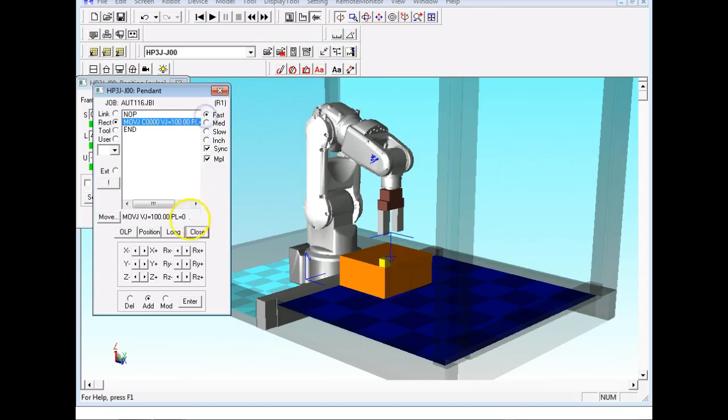If I want it to go down, I just say, okay, then I'm going to go down here. I'm going to go minus Z. Now look, it's moving multiple joints to maintain the orientation of the tool. But I'm not concerned about, okay, do I need to move joint 1? Do I need to move joint 2? Do I need to move joint 3? So Cartesian jog is probably one of the most popular ways to jog the robot.